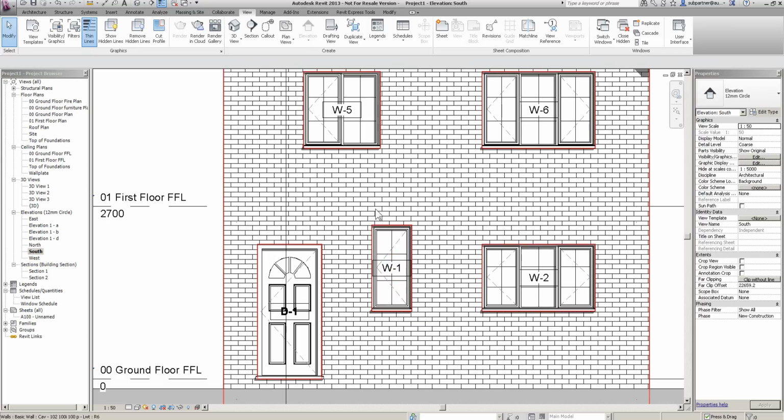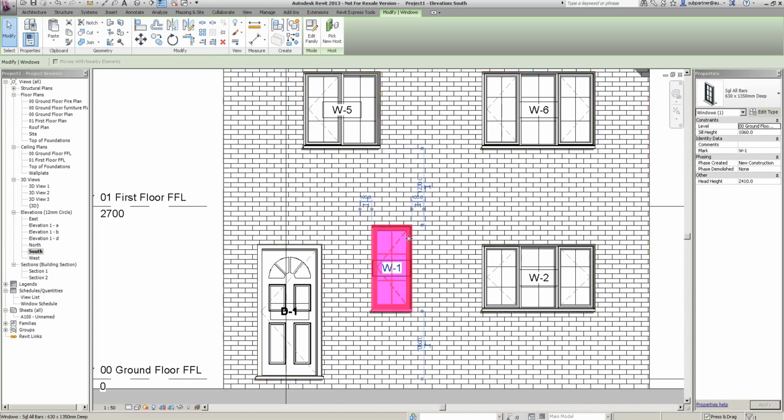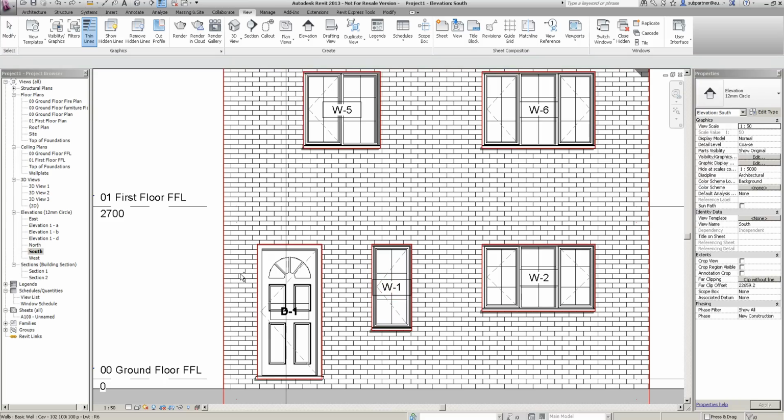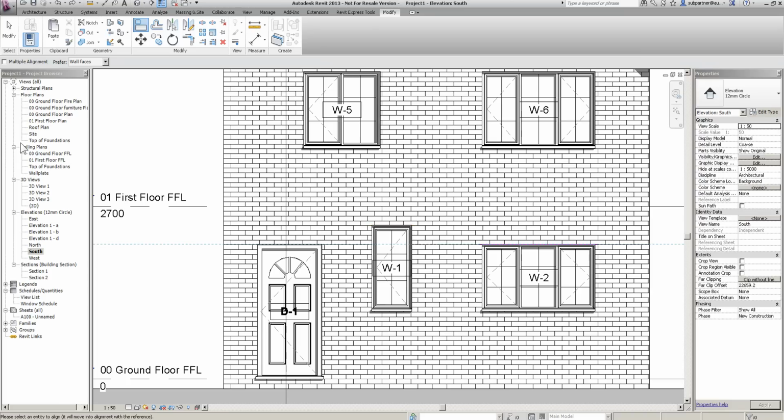Okay, now I can change this in my plan, using in my elevations or plans, several tools. I can highlight it, just change it in here to 2110. Done. Okay, so Control Z that to take that back up. I can use my align tool just to align that to the top of there like that. Okay, you know how to do that. But what I can also do, just to show you,